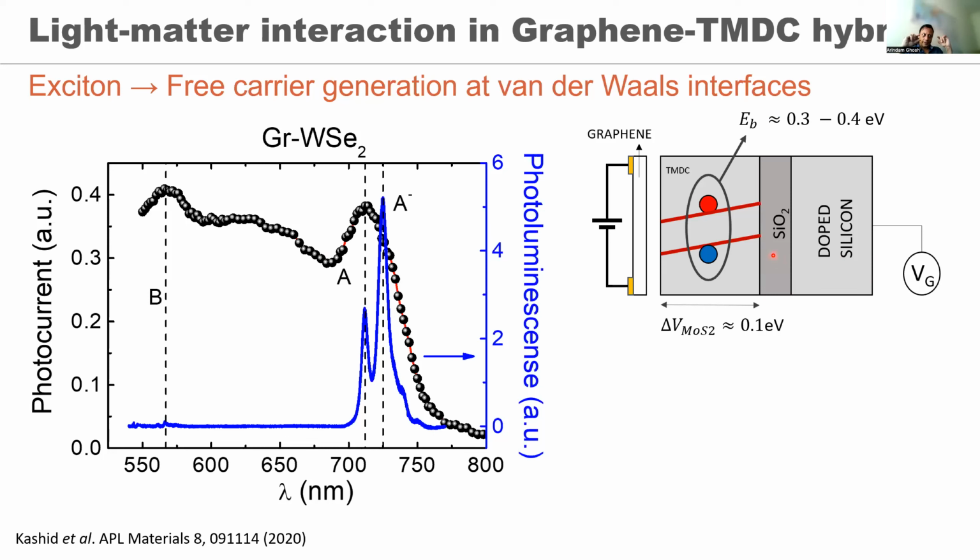First of all, the optically active parts are just two in this case: graphene and the transition metal dichalcogenide. The two other parts in the cartoon in the video that I showed are, for example, two layers of boron nitride. They are essentially encapsulation layers, so they make sure that your device is not exposed to air. But there are ways, and we are working on it now, in which we use more than two or three layers.